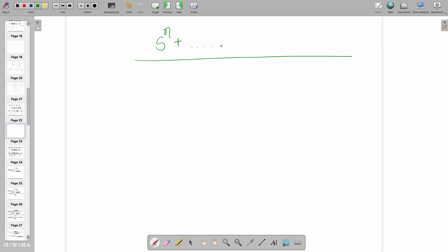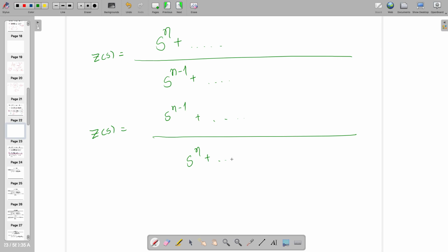So what I am saying, if there is a transfer function, there are two possibilities. One possibility says that the numerator has higher degree than the denominator, or the other case, the numerator has lower degree than the denominator, and this difference will always be 1 or maybe 0, right? If you are seeing the first case, which is the numerator has higher degree, then you are going to see inductor as the first element, or you can say that there is a pole at origin.